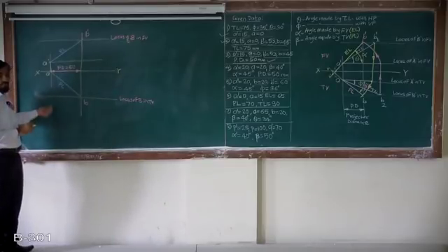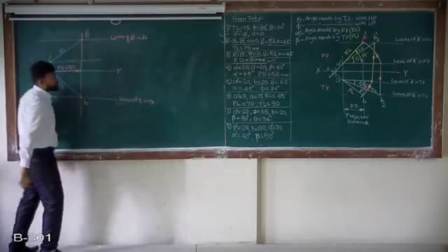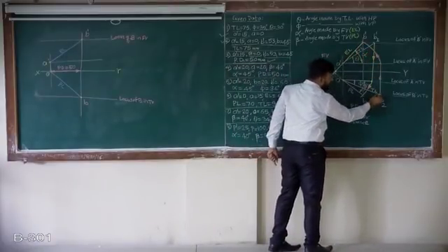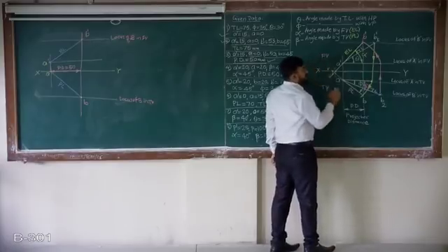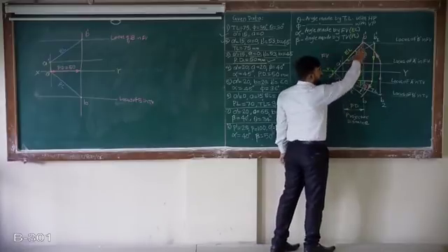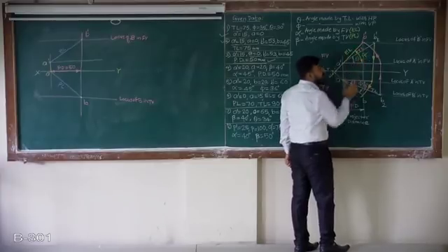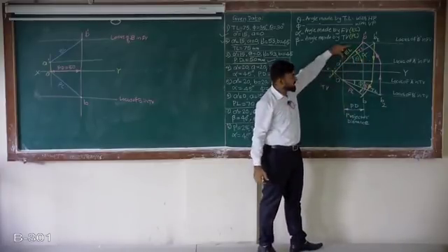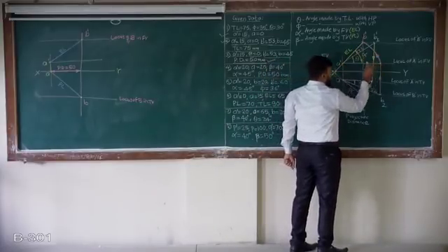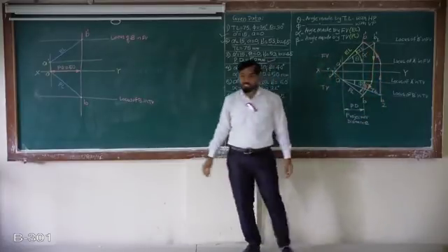Then how to find the true length for this problem? Again, the same concept as the previous problem. I know the elevation length, so how do I get this point as a true length? I will rotate this EL in reverse on the A dash locus, or simply make this EL parallel to XY, and then again project onto the locus. You will get point B2.